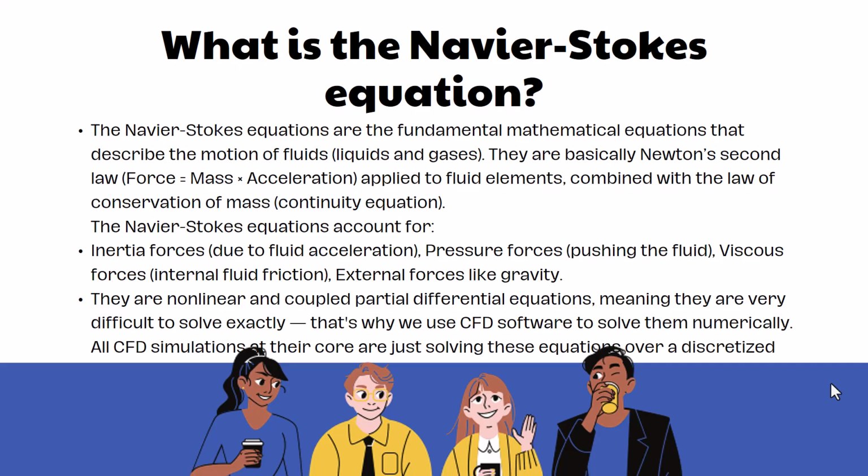So it takes into account inertial forces, which are due to fluid acceleration and fluid motion, then pressure forces, viscous forces, and gravity. These equations are non-linear and coupled partial differential equations. In real-life scenarios it is impossible to solve these equations analytically. That's why we use CFD software to solve them numerically.